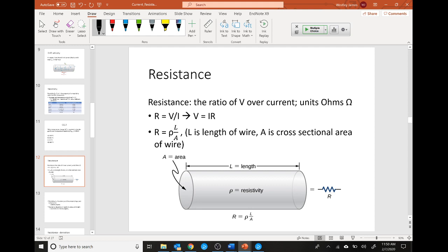So you can see that in the previous slide. We showed this last time. Resistance equals resistivity, which is based on whatever material it is, times how long your wire is. The longer it is, the harder it is to push current through that. And divided by the area, the bigger your wire is, the wider it is, the easier it is for electrons to flow. Because really the actual reason is just you have more of them. You have more electrons, so as you put that potential, you get more of them flowing at once. That's where that area comes from.